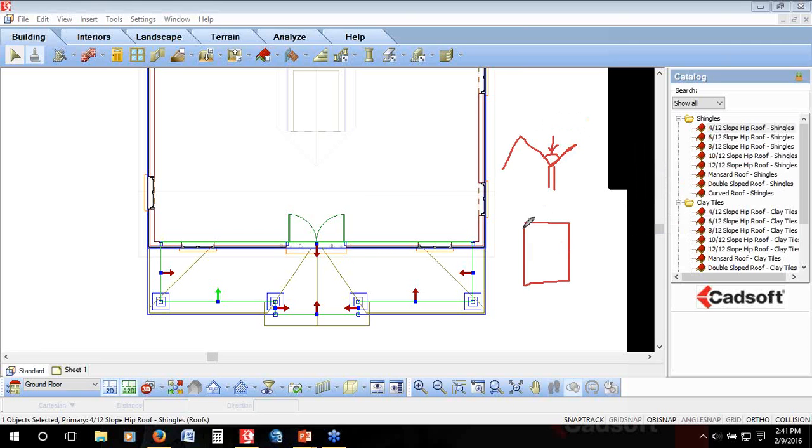But with that being said, if we looked at it in a plan view, here's our existing roof, here's the new roof that he wants you to build. This would remain your hip end, and that's where you're going to call out the slope. So that could be your 8-12 as an example, because it's starting there and sloping up. This would be a gable, this would be a gable, and this would be a gable. So yes, absolutely you can create it.